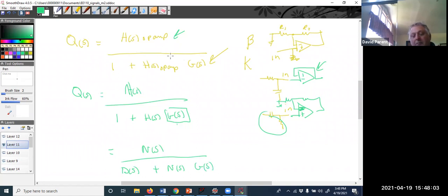And the way to answer these is usually when you let open loop gain go to infinity, that's when you get your ideal function. There are a lot of examples on that, but maybe now you can see that it's almost the same thing. It's almost the same question, except the original thing was already in control.